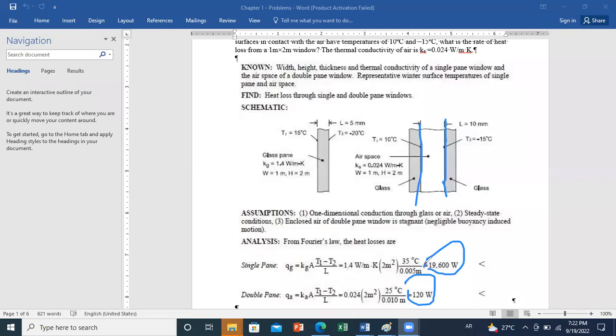But keep in mind that increasing L a lot can have a negative effect, because it's true that if you increase L, the conduction flux will be reduced, but you will then have currents of convection. So you should not increase L in a way to have convection dominant over conduction.